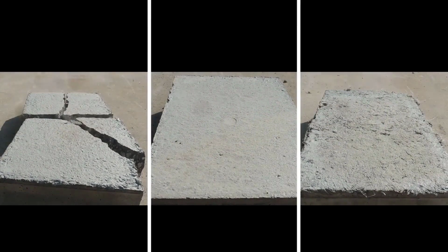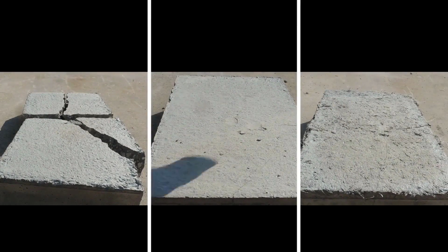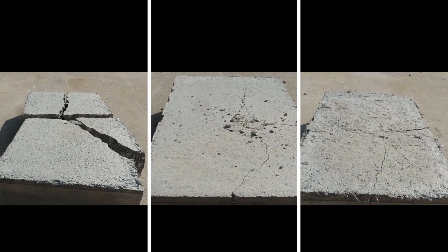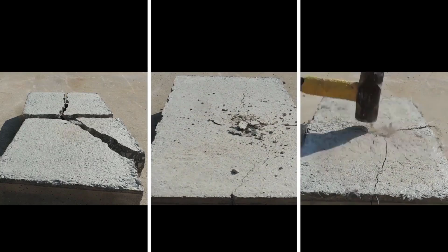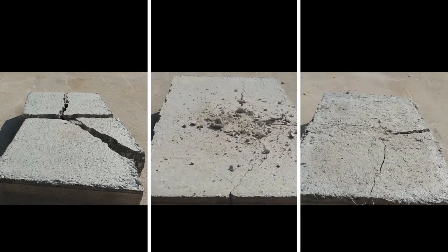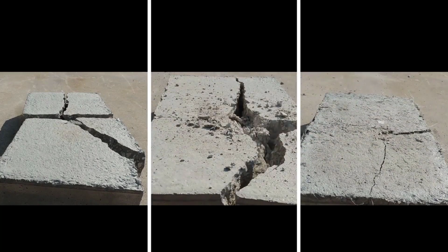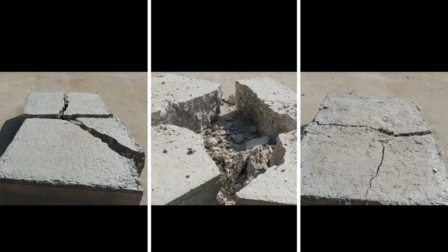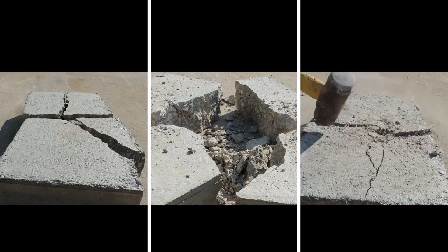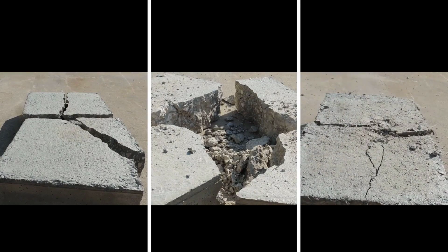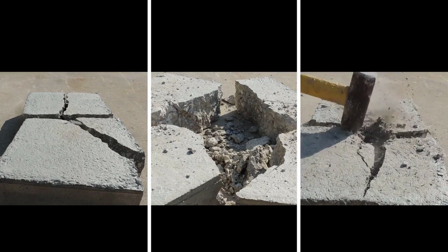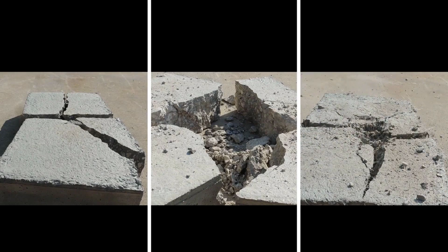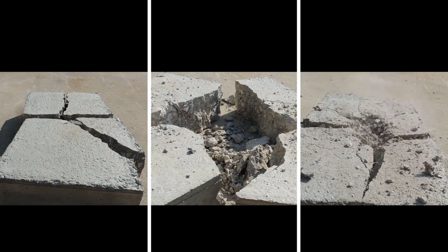Okay, so the first portion of the video on the left is one that's unreinforced. As you can see, after just one hit, the concrete not just cracks, but also splits apart. That's because no reinforcement is there. While in case of the other two, the concrete cracks, the fibers or the reinforcement don't actually stop concrete from cracking, but after the concrete cracks, you do get some post-crack strength or some kind of crack control out of both materials. So this is the first type of benefit that we get out of using fibers: fibers provide some post-crack strength to concrete.